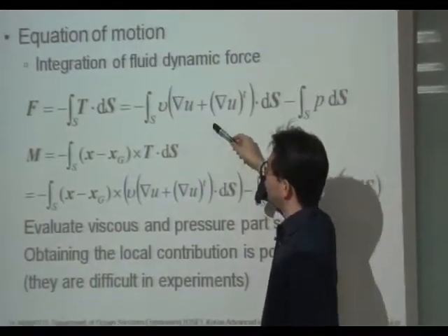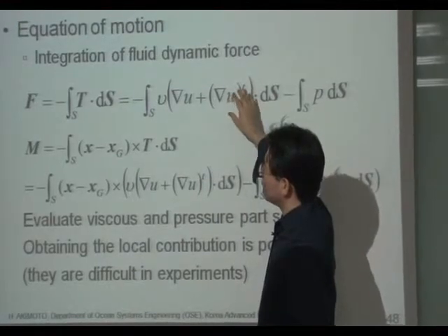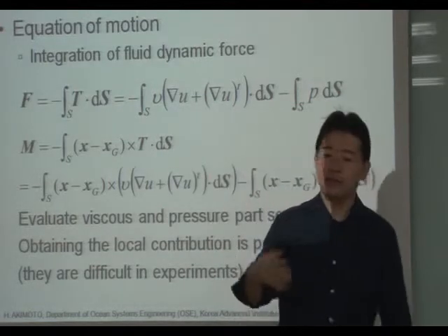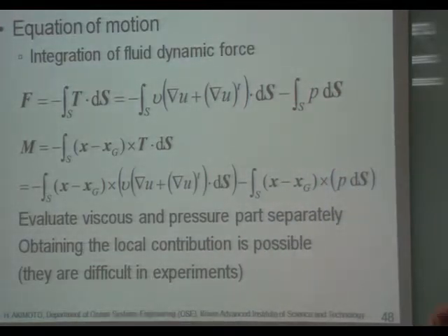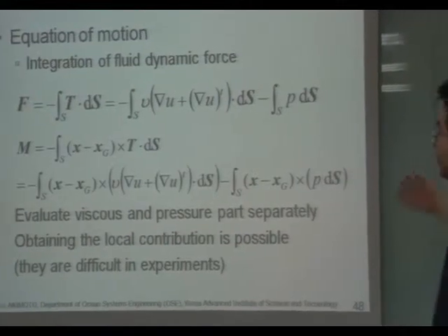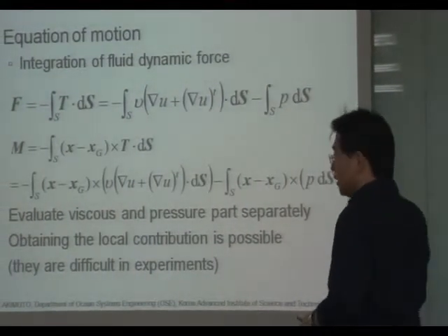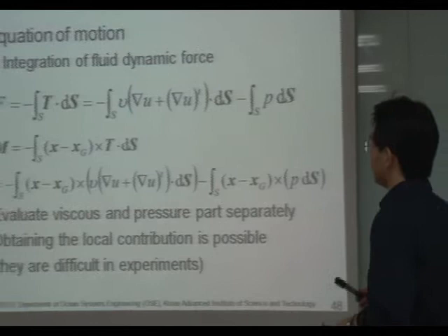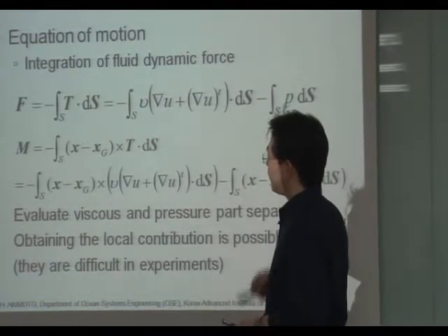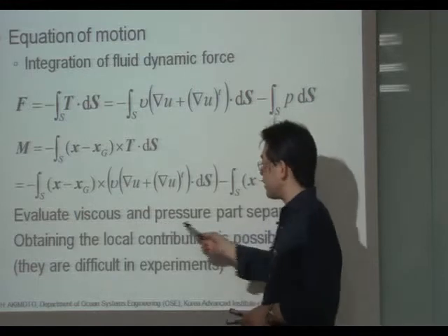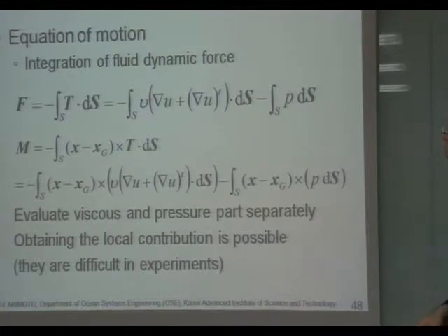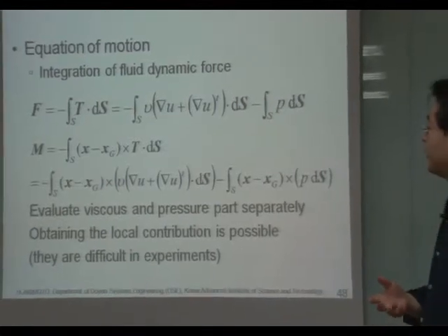So usually we will calculate the integration of force and the moment in a single routine, because most of the calculation is the same. The important point in this consideration is this one. It will provide evaluation of viscous and pressure parts separately. It is very important. In experiments, we cannot get these two effects separately. They are mixed.